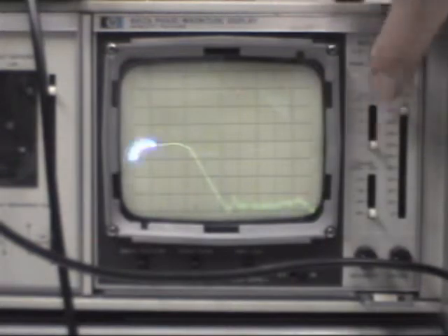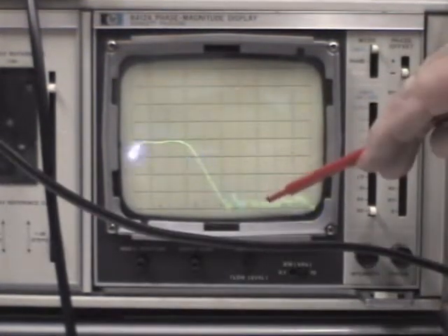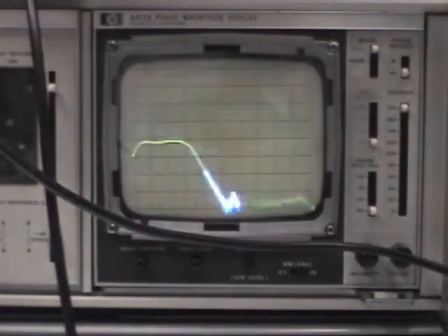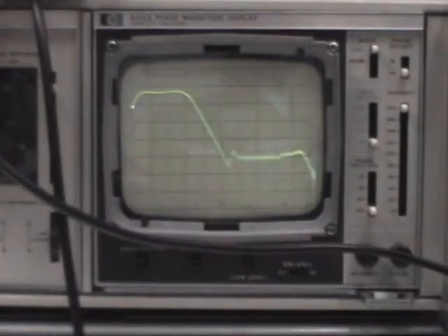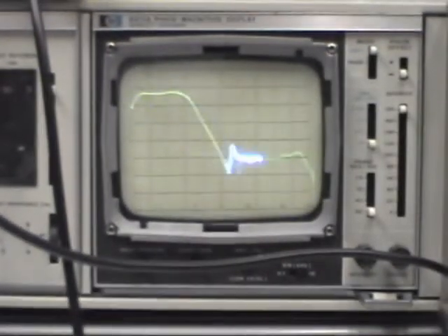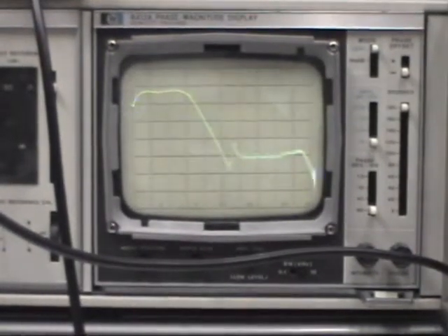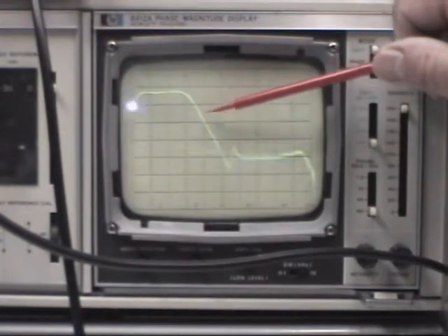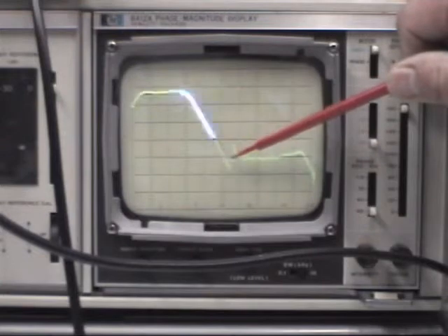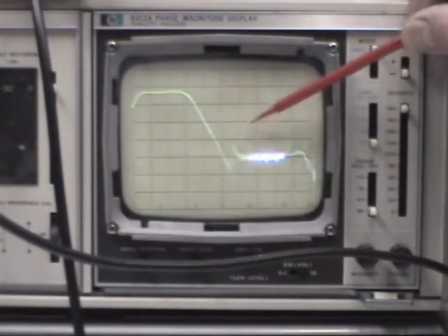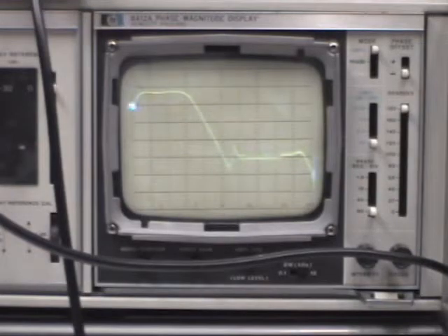If we go back to 10 dB per division, we can see we've got about 40 down here. We can look at this in a little more detail by putting 10 dB of gain in. We don't read perfect up here because I'm getting a little compression on the amplifier there. But what we can see is I've got about 10, 20, 30, 40 dB plus a little, then it comes back up to about 40 dB for the low pass filter. Let's look for that in a little more detail.